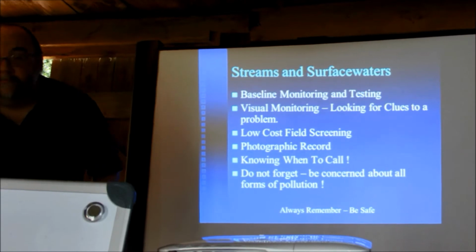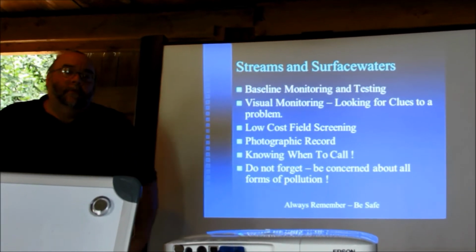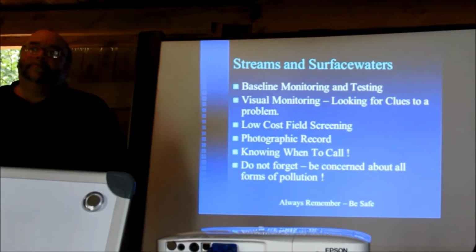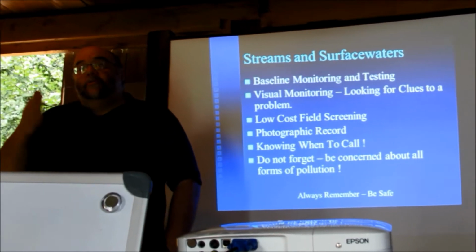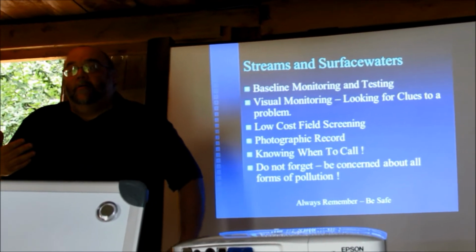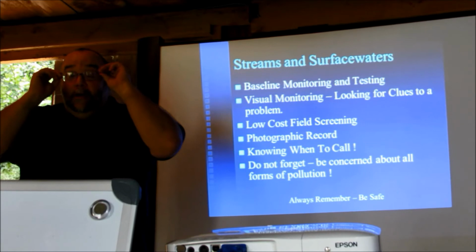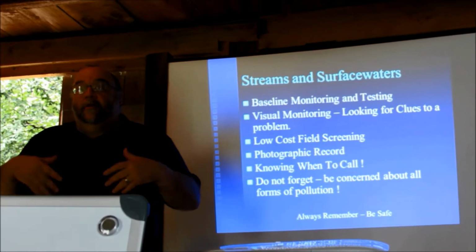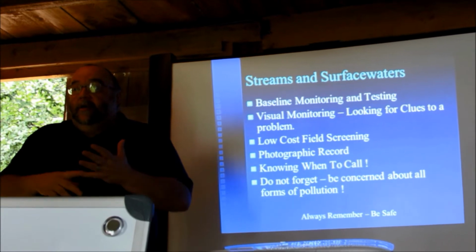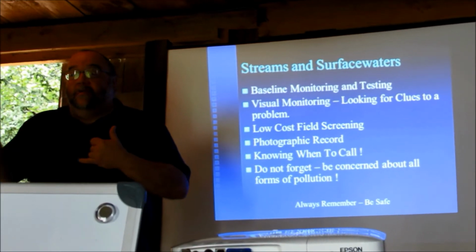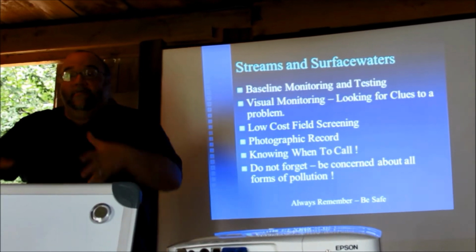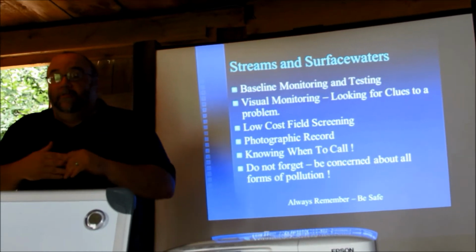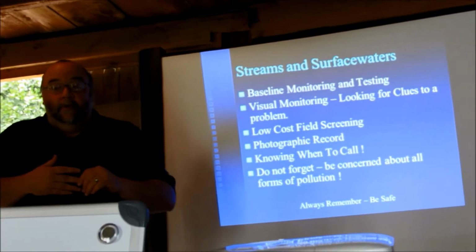Can you get high bacteria because of gas drilling nearby? Can that affect people's wells? I wouldn't say it would be the most typical, but is it possible? Any well that's vulnerable to surface water or near-surface water influence, and you can have an activity doing foundation digging, it rains and you get runoff and it goes right into the rock. You can move bacteria easily that way.